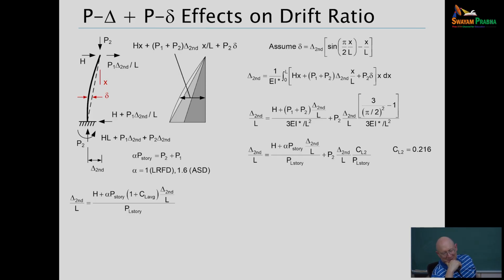Now that we've defined a term C sub L, when Bill LeMessurier published his seminal paper that introduced a lot of this, in the AISC Engineering Journal in 1977, I typically don't use it and don't provide that because it's all in allowable stress design, so you've got a lot of ugliness to work through. But he had charts where you could go in and calculate a C sub L for every column in the frame. Now that's a lot of work.